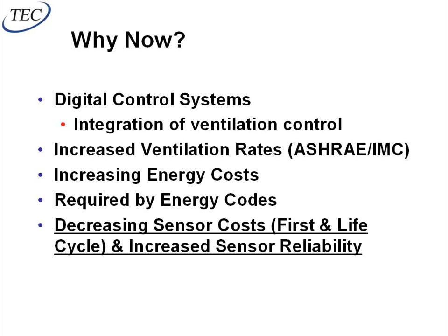LEED buildings have played a part in this as well. Not only are you trying to save energy on those buildings, but you can also be awarded a LEED point for outside air delivery monitoring. And the way to do that for densely occupied spaces is to use CO2 sensors. And then for non-dense spaces, you do an outside air CFM station. But for dense spaces like auditoriums, theaters, those kind of places like we talked about, you have to use CO2 sensors if you want to get that point.